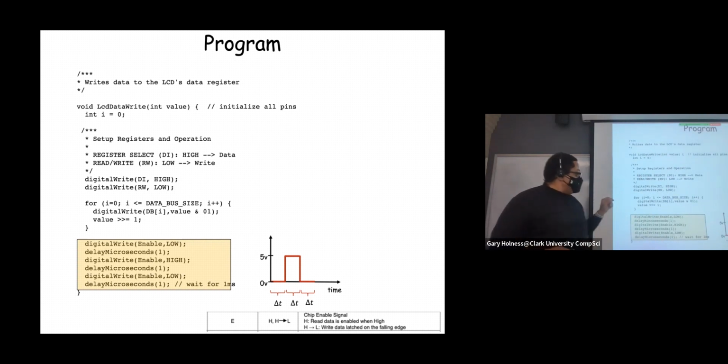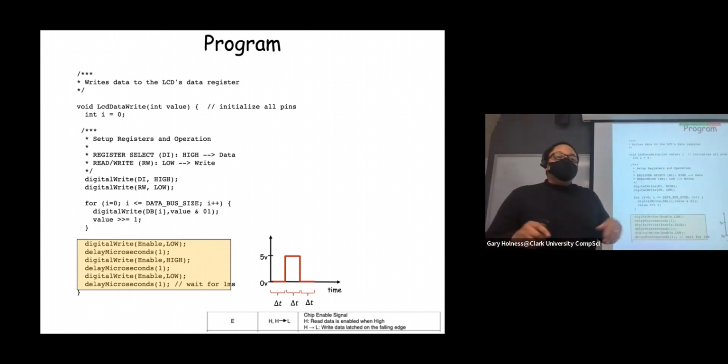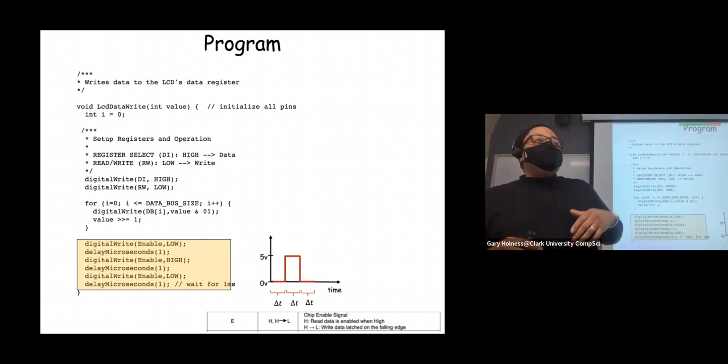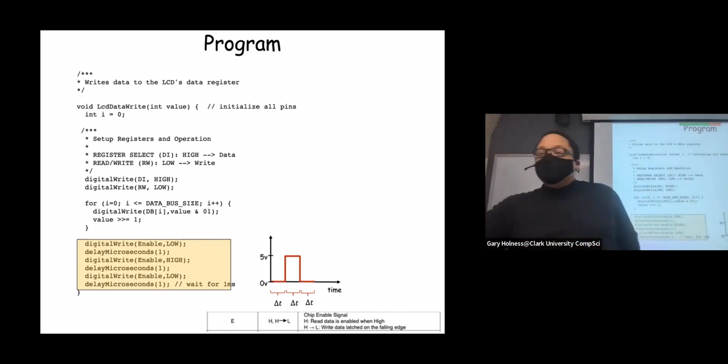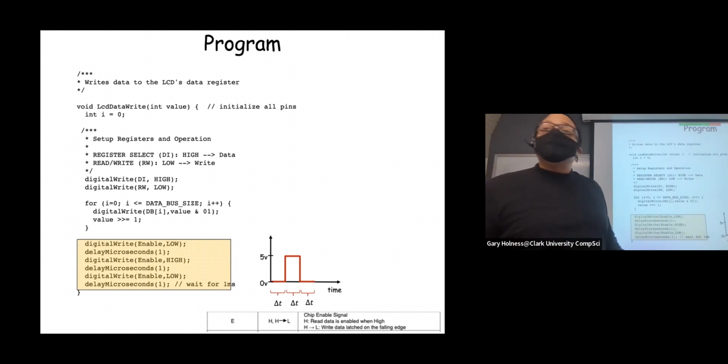And so that's different from the data, and the data is the ASCII code that it's going to display. Because you send the data, maybe you clear the screen with this, and then you send the ASCII code for hello, and it displays hello in that location. Okay, and so it's always command, data, command, data, command, data. Okay, any other questions? No?